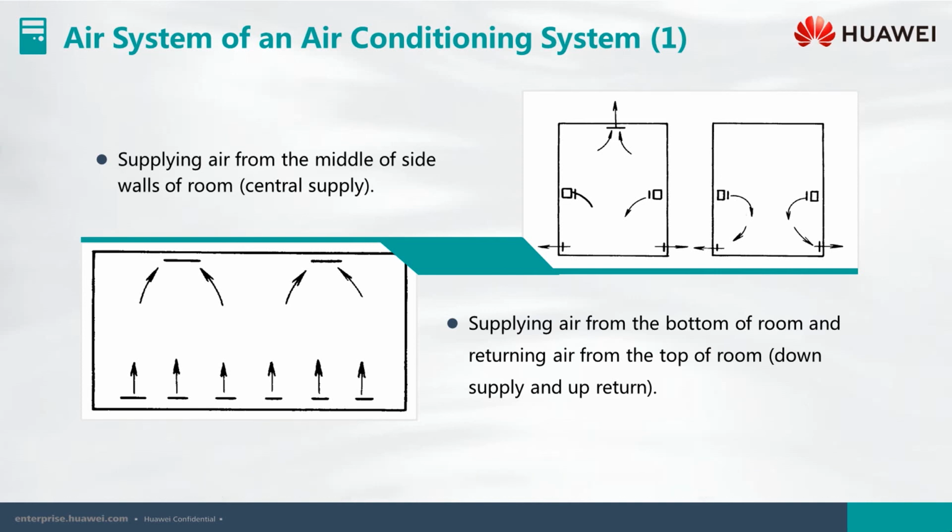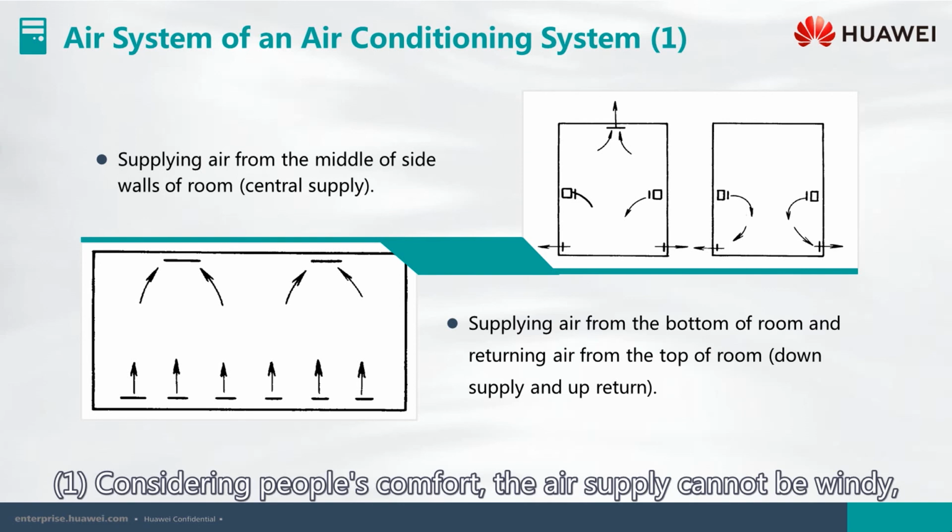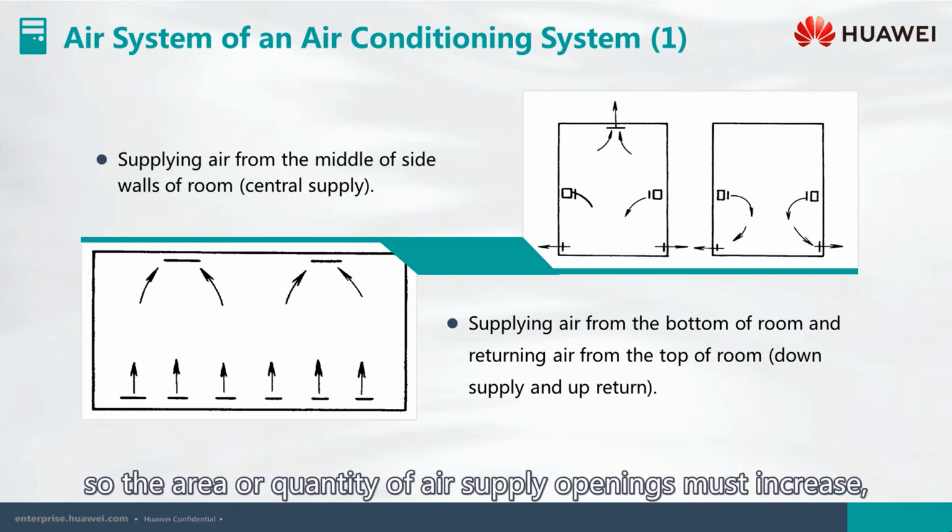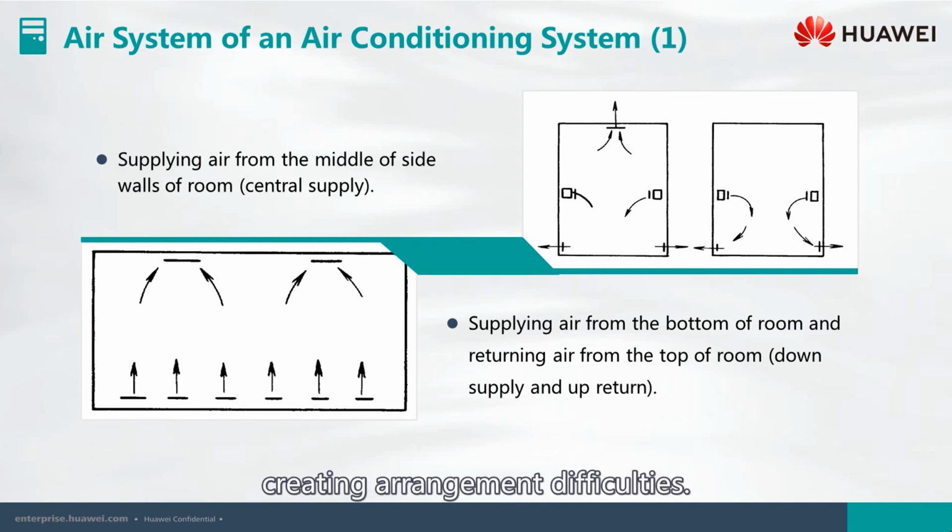Disadvantages. 1. Considering people's comfort, the air supply cannot be windy, so the area or quantity of air supply openings must increase, creating arrangement difficulties. 2. The ground tends to accumulate dirt, which affects air supply cleanliness.